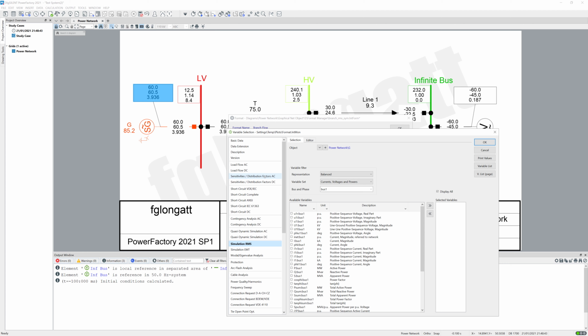I don't know if you noticed, but when we were running load flow, PowerFactory automatically pointed the result variables into the load flow tab. But right now it's indicating, in black color over there, RMS simulation, because we want to get the internal values coming from the RMS simulation, okay?